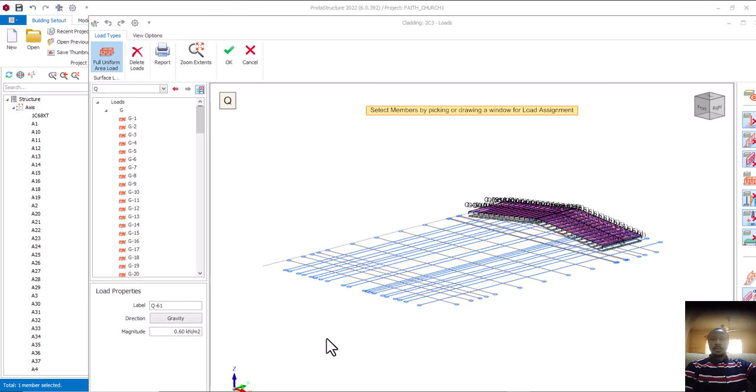So when you do your calculation of your POP, the density 8.5 multiplied by the thickness, which is 0.015, whatever you get plus this 0.05 gives you the dead load of your ceiling, which you now add to the load of the kind of roofing sheet they are using.